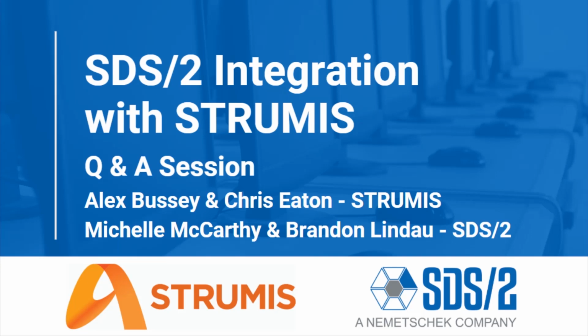That concludes today's webinar on the SDS2 and STRUMIS integration. We covered exporting the BSWX file out of SDS2, importing into STRUMIS and updating the attributes, loading our trucks in Fortosi, and bringing that information back into our STRUMIS contract, and finally finishing with the color coding by attribute inside of SDS2 detailing. Now we'll give you a few moments to type in your questions and start the Q&A.